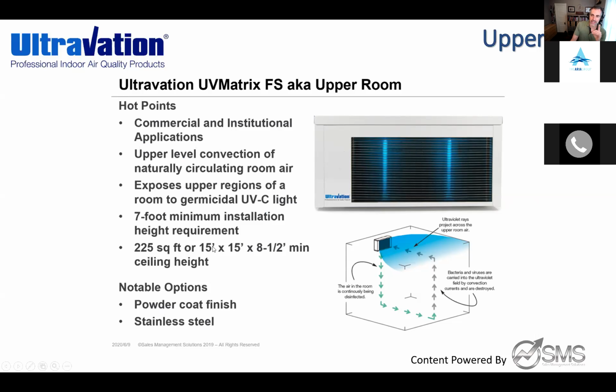You're still going to be required to have a minimum 7 to 8 foot mounting range, because you don't want people to look straight into the box. So you want this above eye height. Unless you're employing NBA players, football or basketball players that are like 7 feet high, this will be fine. But this is meant to help increase air disinfection rates in wide open spaces.